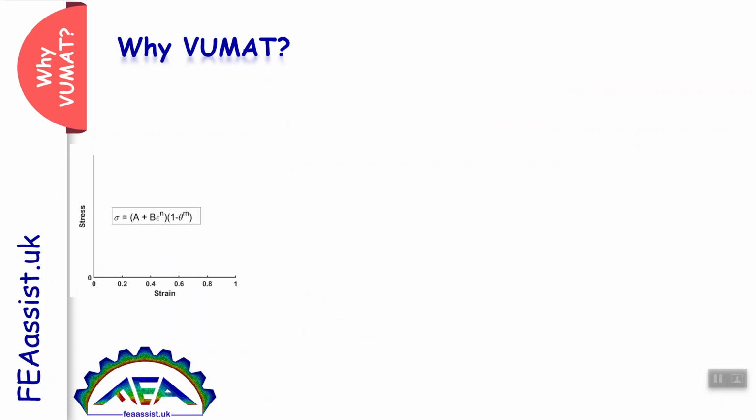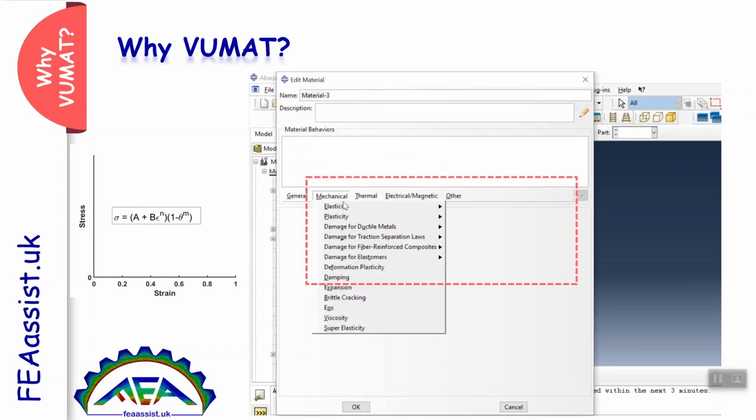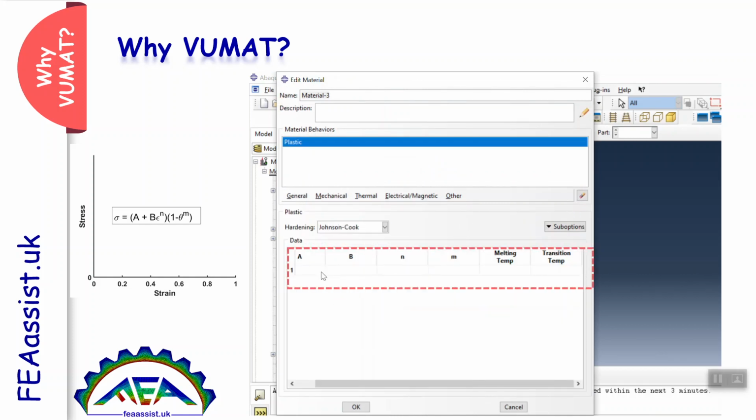If you want to solve your problem more precisely, then you need to have the constitutive behavior or constitutive equation of your material. Your material mechanically obeys some rules. If you have an equation and it is included in Abaqus, then you can go to Abaqus again, to property, materials, mechanical, and instead of entering the points, define the behavior.